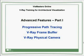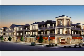As another example, I haven't talked about the VRay physical camera up to this point because this particular feature can completely change the way illumination in your scene appears. If I gave this completed scene to a VRay user with very little experience and then asked the user to replace the standard camera that was used to render this image with the VRay physical camera, I might get an image like this back, or maybe something like this. So until you have a good understanding of all the other things that have been discussed in the first 6 modules, you probably shouldn't try using things like the VRay physical camera because you'll just be making things hard on yourself. It would be like putting the cart before the horse.